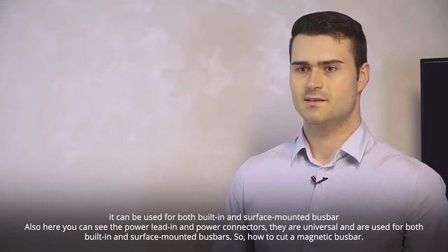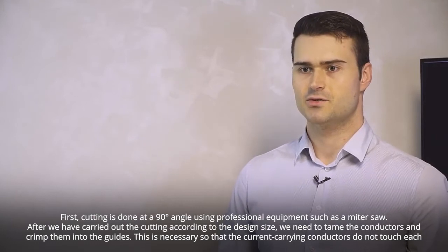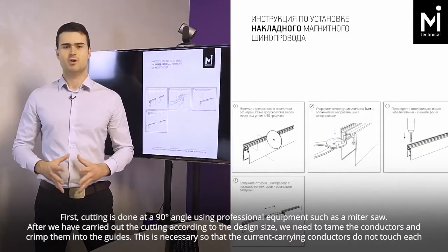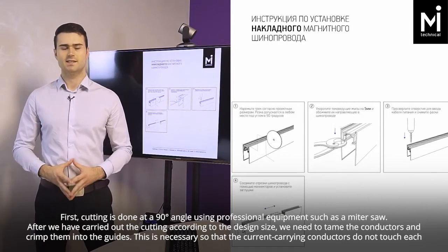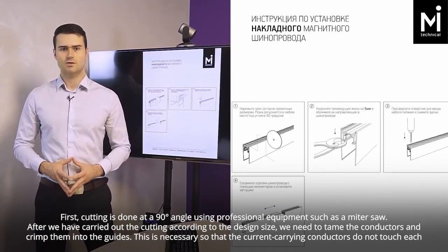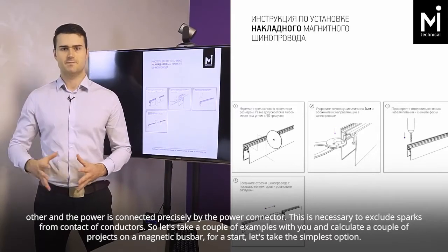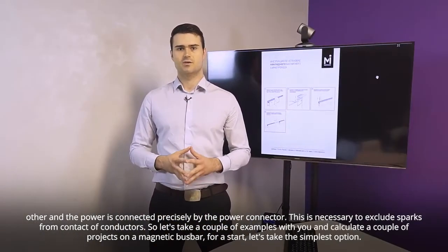So, how to cut a magnetic busbar? First, cutting is done at a 90 degrees angle using professional equipment such as a miter saw. After we have carried out the cutting according to the design size, we need to tame the conductors and crimp them into the guides. This is necessary so that the current carrying conductors do not touch each other and the power is connected precisely by the power connector. This is necessary to exclude sparks from contact of conductors.